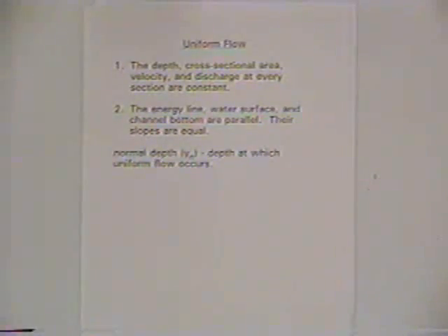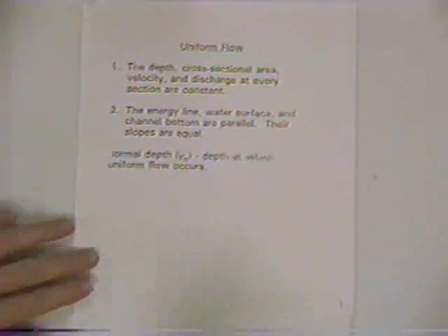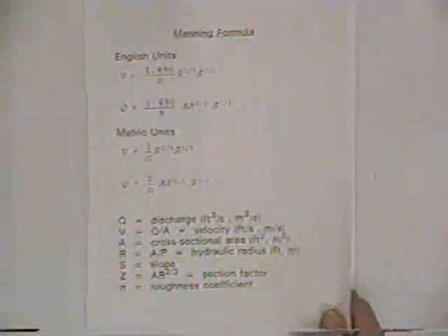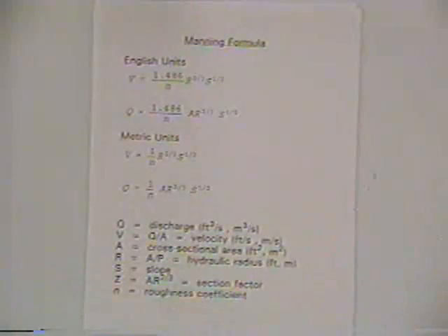And so we're planning for open channel flow problems on the exam to limit themselves where we recognize that this is a uniform flow problem. And so we can use the one equation that's provided in the reference handbook, and that's Manning's formula, to deal with flow situations as far as a uniform flow equation. Now, energy equation, the basic concepts are equally valid to uniform open channel flow as well as pipe flow.